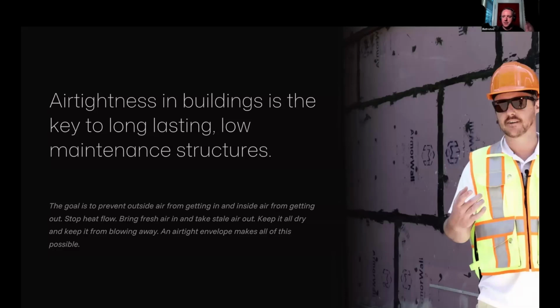And if there are pathways for that humidity in the air to come through the building envelope where it might hit a cooler surface that's been cooled down by air conditioning, it can condense and then grow mold and then rot and just cause that building to not last as long as we want it to and create an unhealthy space for occupants.